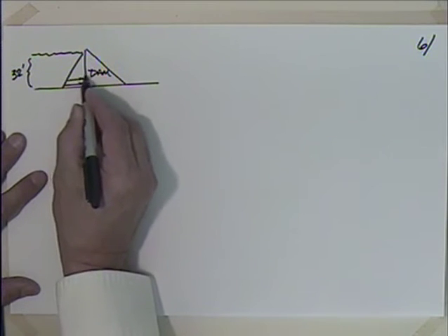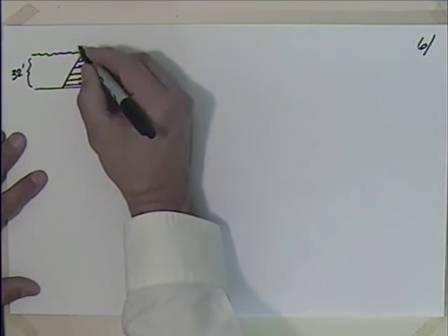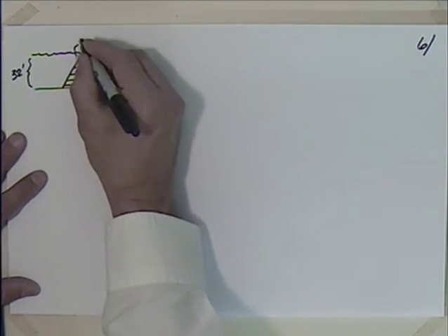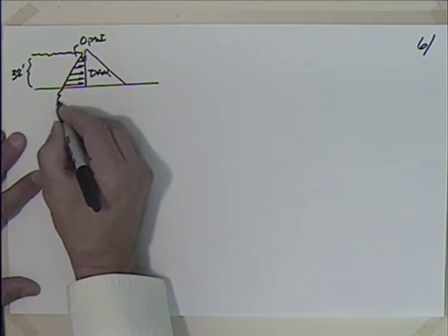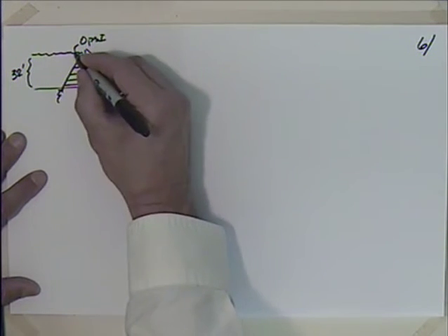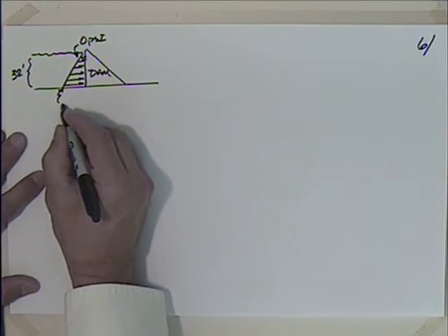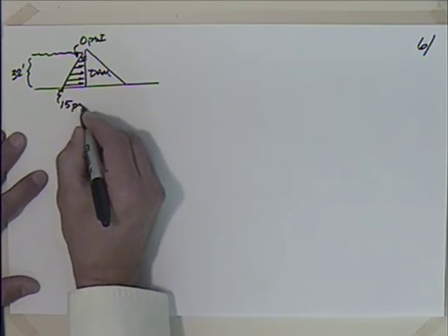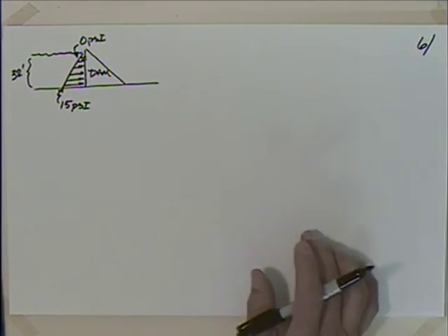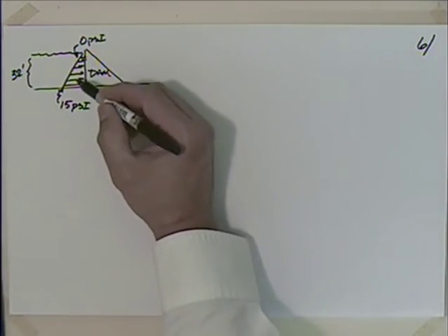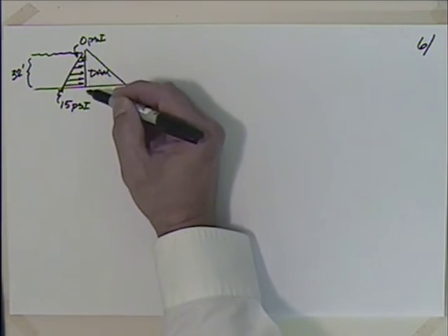Okay. So if I look at the pressure distribution here, if I look at a gauge pressure, I have 0 psi at the surface, and down here I have about an atmosphere, 14.7, or why don't I just call it 15 psi there. Anyone that's maybe gone down and stood on their head at the bottom of the public pool or something recognizes there's more pressure at the bottom. Your ears hurt more there than at the top.